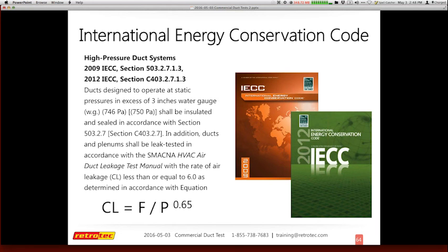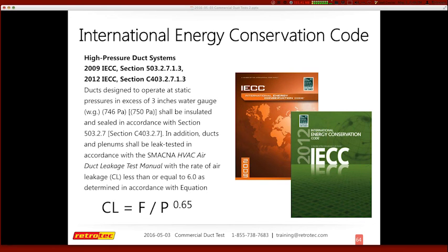It automatically puts in the leakage class for the square and round ducts down here, so a lot of this is automated. We've got this set on pressurization. When you put a value in for test pressure, let's put in the area for the ductwork first, over towards the left in the yellow, a little further down.